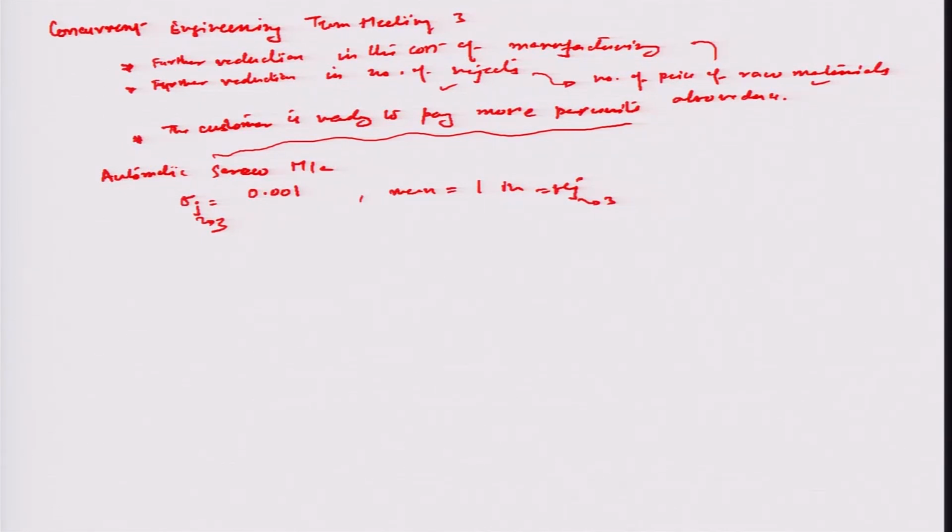Obviously, the unit processing cost of such a machine is very high. The unit processing cost in this particular case comes out to be equal to $12 per piece. Other data are pretty much similar to previous meetings. In this case, although the unit processing cost is more, it may happen that the overall reduction in the rejection is higher, because of which the number of parts that you have to machine may be lesser in order to get the required amount of parts for the manufacturing process.